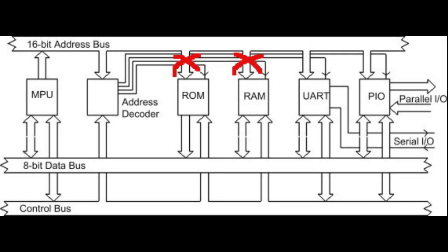Another thing that may happen on an actual microcomputer system is this: since there are many chips that need to get the same address lines from the CPU, there are other chips called buffers that just copy the inputs to the outputs. So the CPU just drives the buffer inputs, and the buffer outputs go to all the other chips. So what happens if the address buffers have some faults?